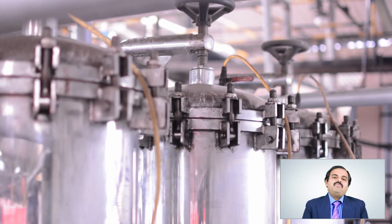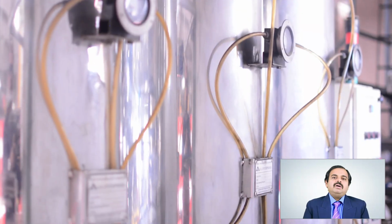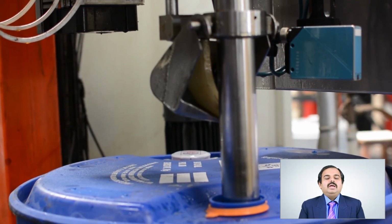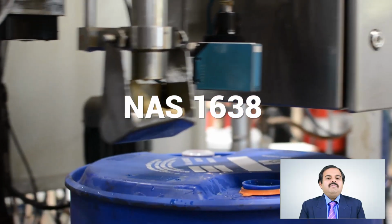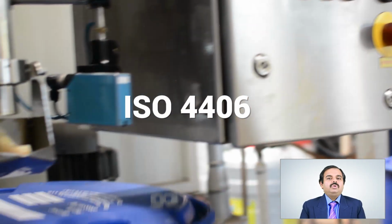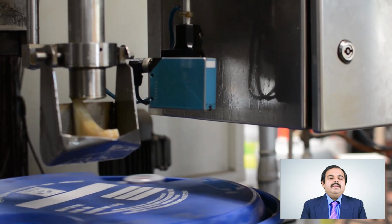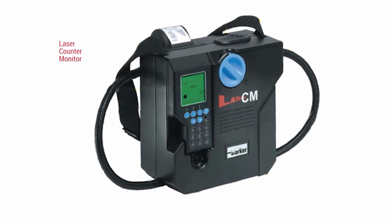The cleanliness of oil is another important aspect. Turbinol grades are filtered to fine levels before filling in containers. The most common cleanliness standards are the NAS 1638 and ISO 4406 standards. These standards measure the particle size and the count in 100 ml of oil. This is measured using a laser counter monitor.